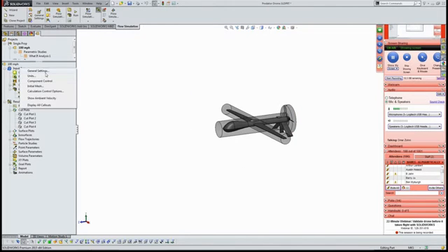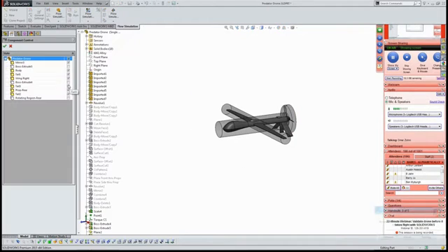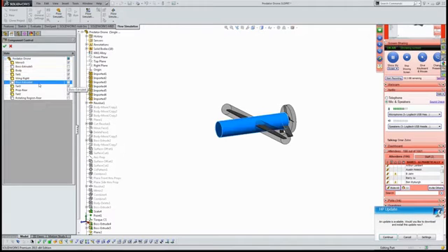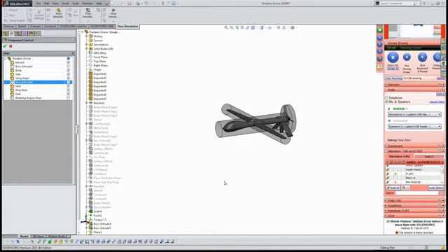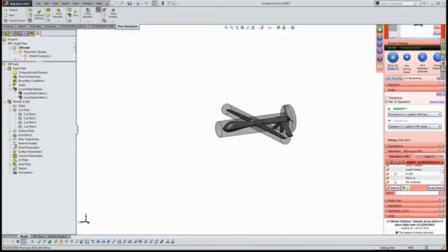In addition to that, I'm coming to my component controls and telling the solver, hey, these bodies, do not include them. They're not solids. They're simply there for a mesh setting, or they could be a place where you wanted to monitor results. So you've got that kind of control. There are lots of different mesh controls that you can use.